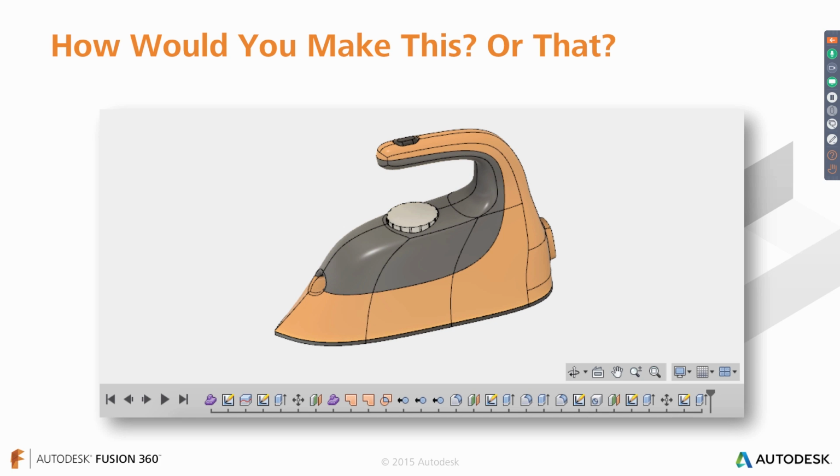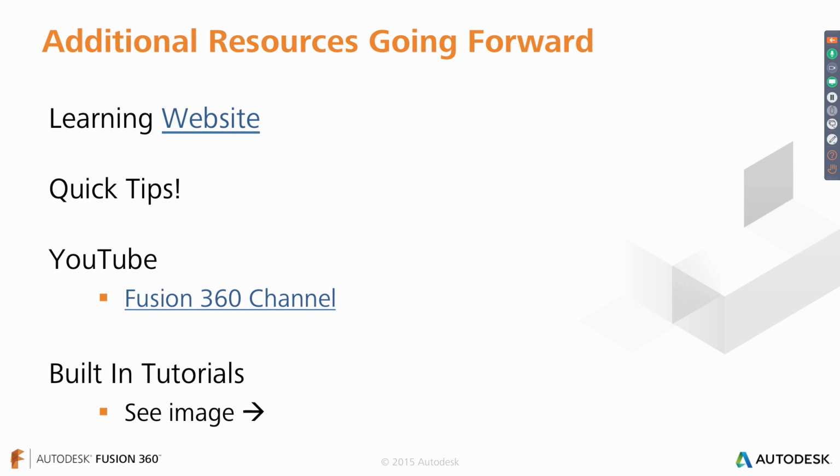What I would recommend to you, new users, is get into the gallery, maybe the Fusion 360 gallery, open up some existing models and actually just use that slider at the bottom, the timeline slider. You can learn a lot about how someone built something and understand quite a lot that way.